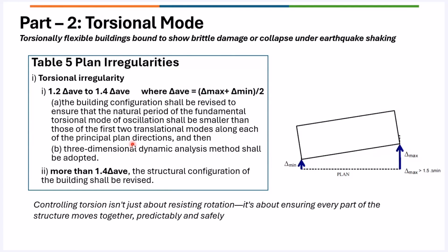So as we discussed earlier, the torsion occurs when the lateral load acts off center from the building center of mass or center of stiffness, right? The strategies we have are only about the planning, keeping the building as symmetric as possible, and the mass distribution even, and also the stiffness distribution even. Without that, there is no shortcut to avoid the torsional mode.